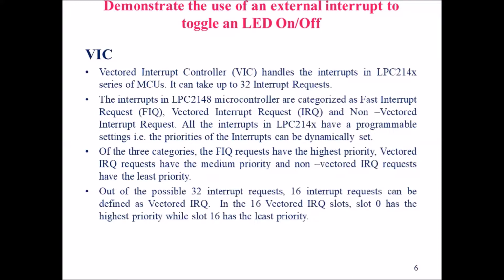It can take up to 32 interrupt requests at a single time. In LPC2148, the vector interrupt control takes up to 32 interrupt requests. So the interrupts in the LPC2148 microcontroller are categorized as fast interrupt request, vector interrupt request, and non-vector interrupt request. So basically, it has been categorized into three types: one is fast interrupt request, another one is vector interrupt request, and another one is non-vector interrupt request.